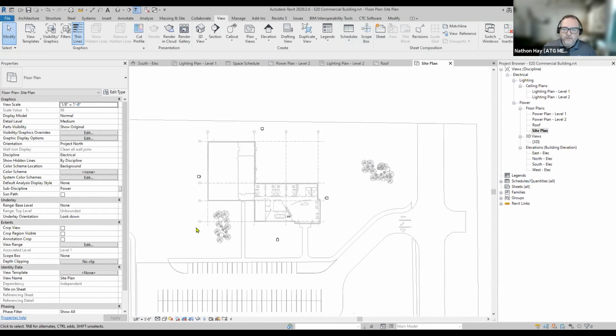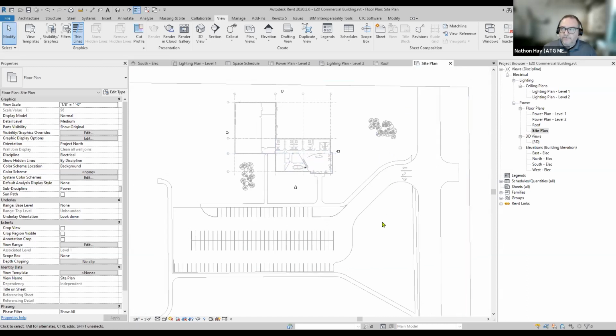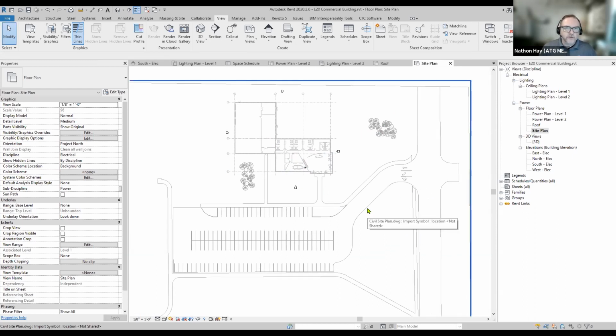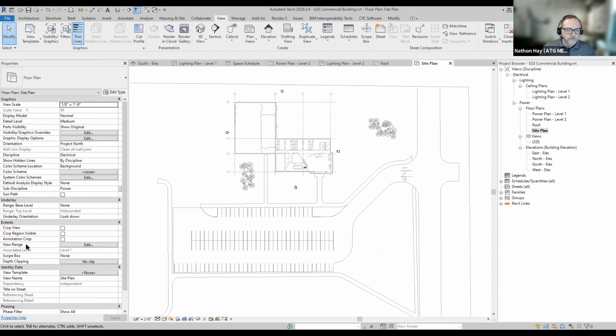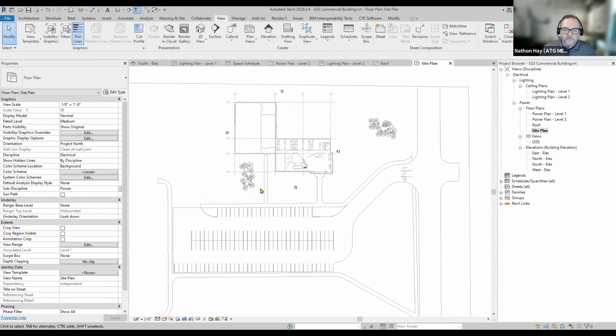The view range. So when you do the site plan, you might have a transformer sitting out here by the road, and you'll need to draw that one conduit over to here to the electrical room and tag it. And you'll need to put the utility right-of-way note. Maybe it'll come from here up this way. So if you're doing it in 3D, you might draw a conduit at 2 feet below ground or something. So we need to edit our view range so that we can actually see underground. So let's just change all these to unlimited. We want to be able to look down as far as we want. We want to look up as far as we want. So just set all those on your site plan to unlimited and you'll be fine. All right. Let's go ahead and save.